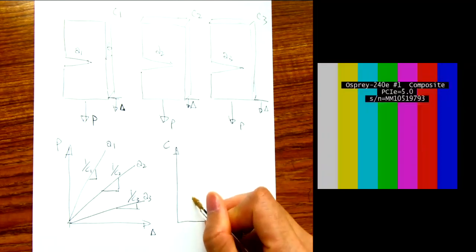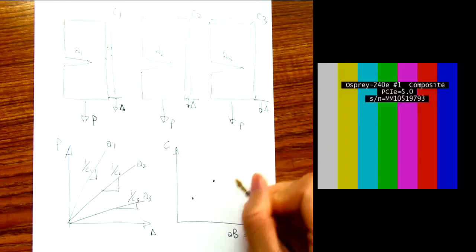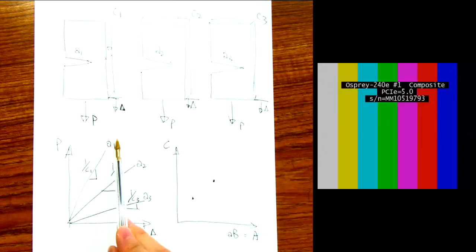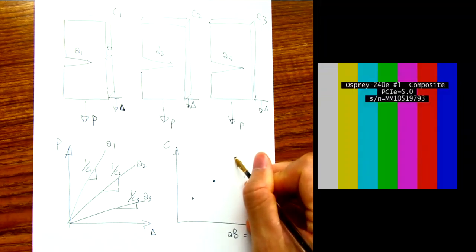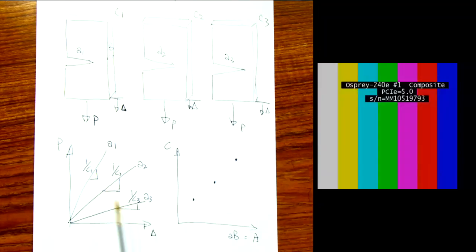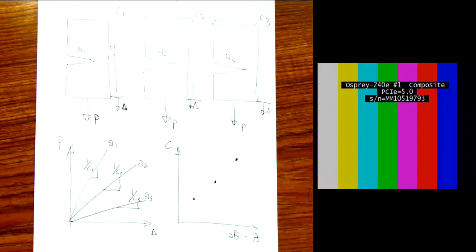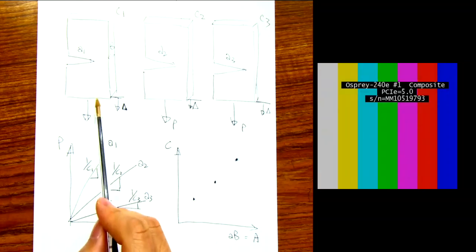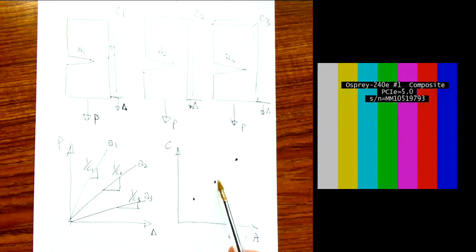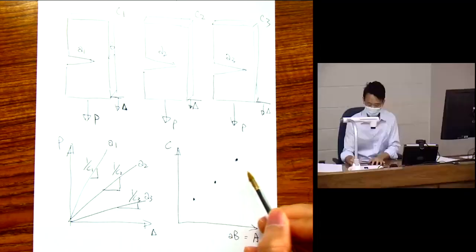Now, let's say that from these three, you transfer over here C1, corresponding to the first crack. Then you plot C2. C1 is going to have the lowest compliance, right? And that corresponds to a smaller crack area, and that is what we expect. So what you're going to see is a curve something like this. It's less compliant means it's stiffer, right? Smaller crack, stiffer, less compliant. Larger crack, more compliant, and so on.